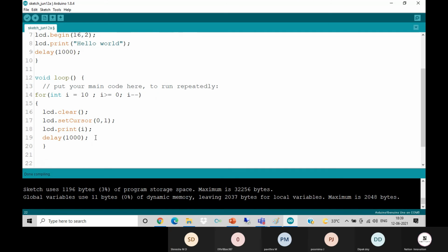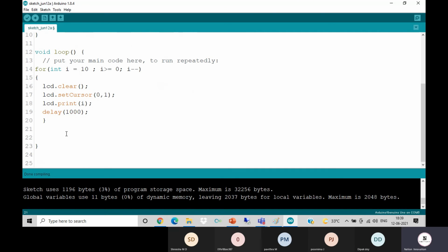And what we can do is, we can now clear the LCD, set the column to 4, and the row to 0, and then we can just print something else, like say liftoff, anything you want to write. It's totally up to you. It depends on what we are doing. It's just for the interfacing purpose, so we can have it. And then let's just put a very small delay in this case.